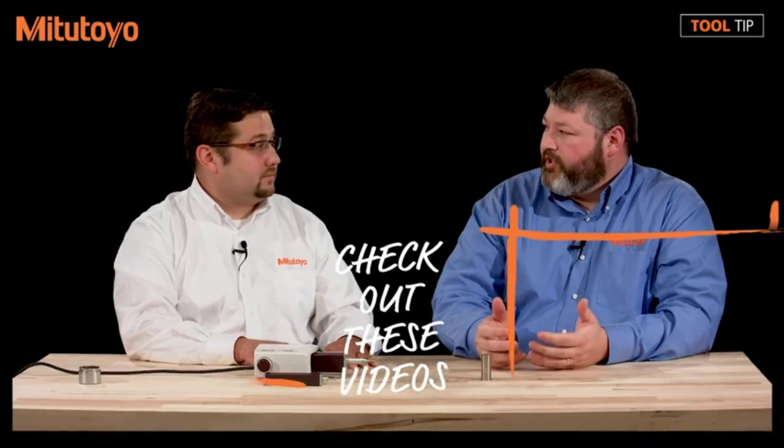So if I had a simple measurement where I just want to measure a flat piece for an RA, a skidded or a skidless would work either way. That's correct. And if I want to start measuring round parts or I want to measure grooves, then I might move into a skidless system. Exactly, and when in doubt, feel free to give us a call, look us up online. We'd be more than happy to help determine which is the best unit for not only your application, but for your budget as well. Well, Drew, really appreciate the time today.